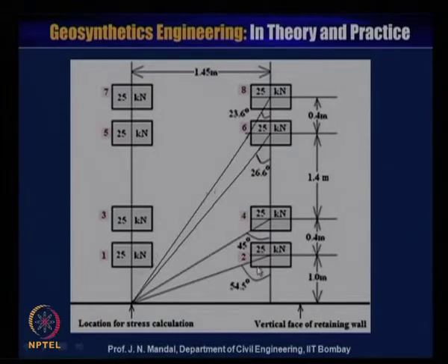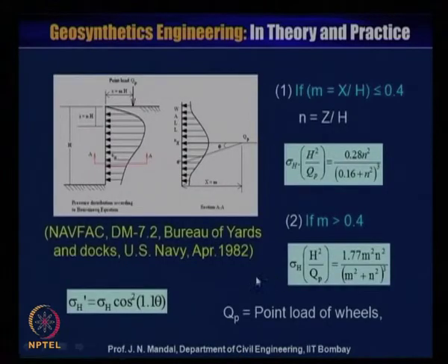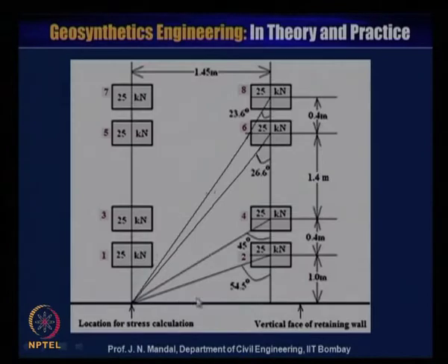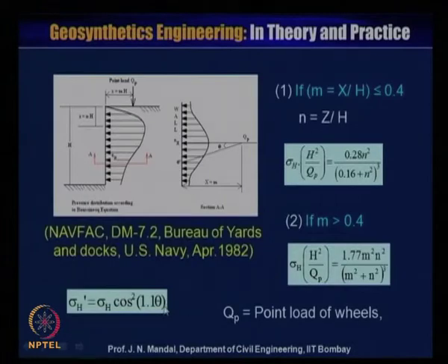For this angle, you adopt the equation sigma h dash is equal to sigma h into cos square 1.1 theta. Theta is 54.5 degree, and sigma h is known to you from before.